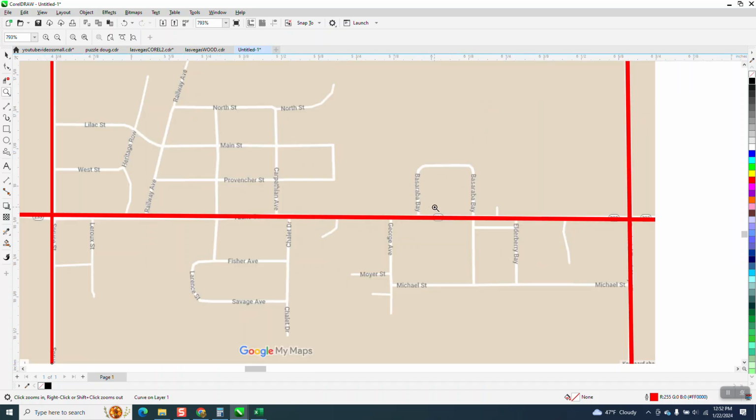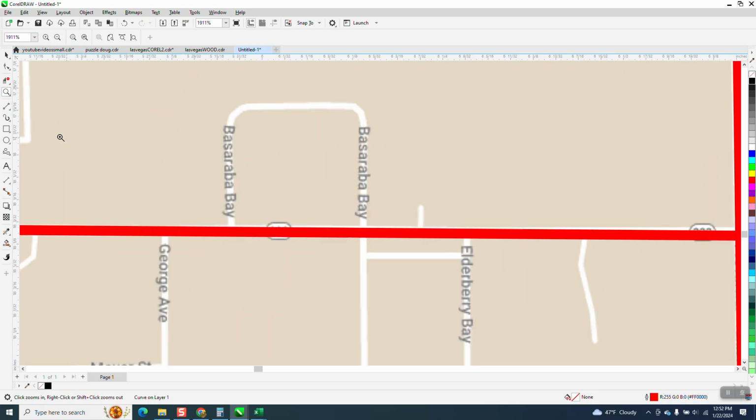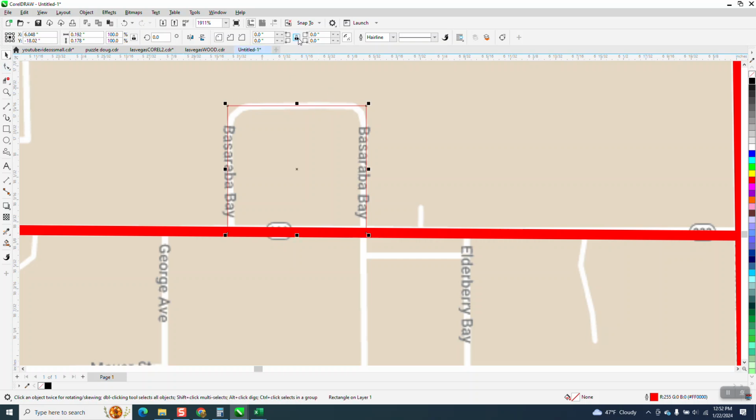And like this particular one, what I would do is, it's got 2 bends in it, take your rectangle tool and just build a rectangle around that. And then while it's still in this mode, unlock, and I'm going to turn the edges to even points, so like 0.05, that might even be too much, 0.04, there you go.